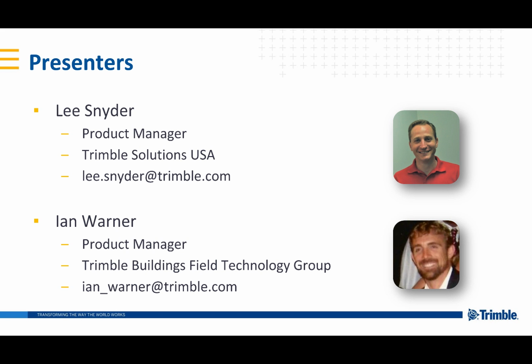Today we want to discuss layout for construction workflows. I'm going to start in Tekla Structures and show how we can create layout points and export those to share them with the field team. Then Ian will show how those can be brought in and utilized in the robotic total stations out on site or also in a fabrication shop.